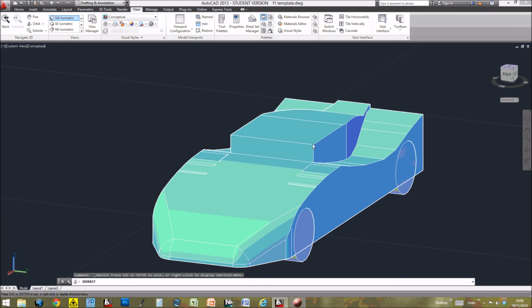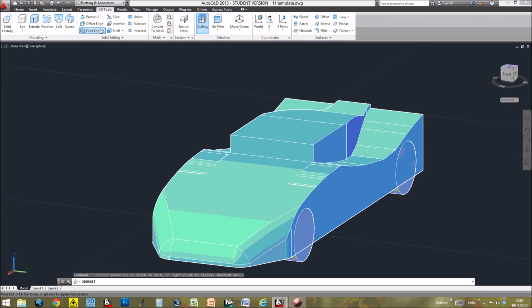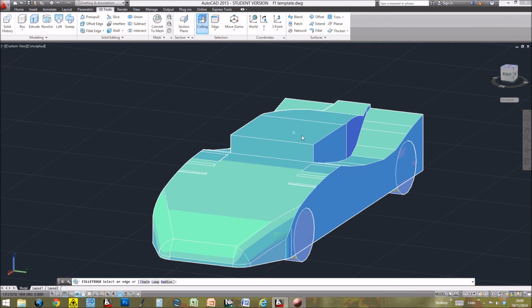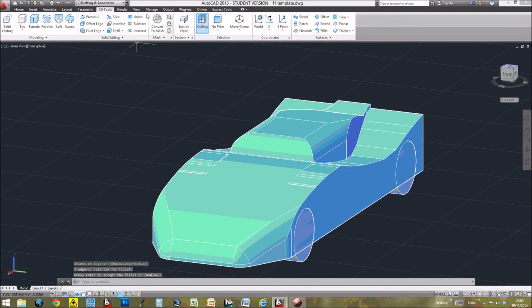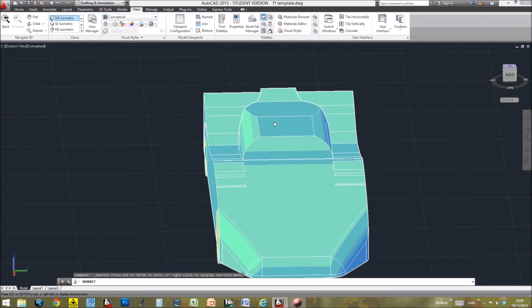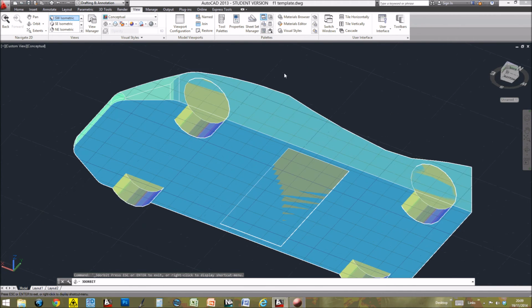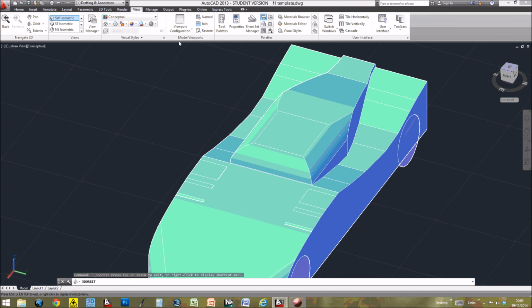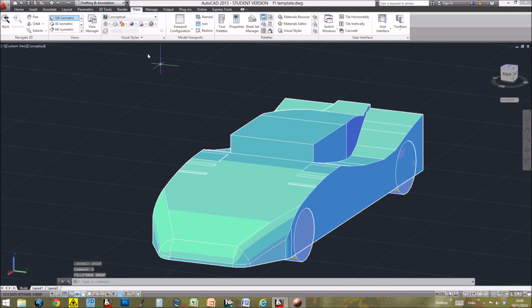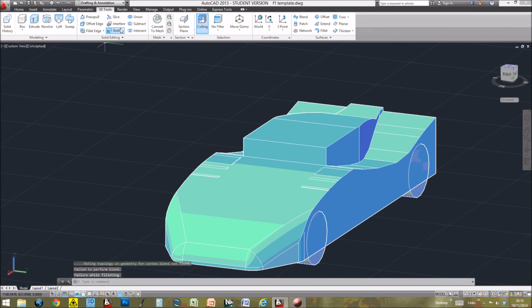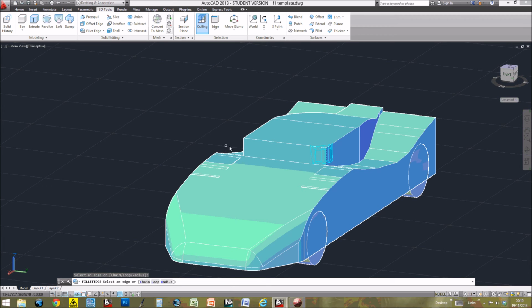Be careful when you fillet these, because if you fillet them too much, as I can demonstrate, let's go to fillet edge. If I fillet edge this and say, okay, let's make this really 10mm smooth, press return. This looks like it's probably going to be okay. If you fillet it too much, the orange box that you've got underneath could poke through. Let me demonstrate that, because if I make this radius bigger, fillet edge, so we're going to select this edge here, we'll select this edge here.